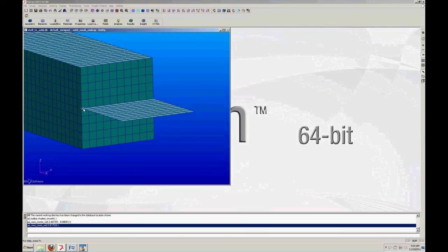Plus, you have to imagine, what would that represent in real life? That would represent in real life that somehow you gouged material out and shoved the plate inside and then welded it in. Maybe that is what happens in real life, but that isn't a common manufacturing thing. So I think in real life the weld would actually be up along here and down here. So in that case, putting a thin layer of surface elements up here and down here isn't a bad way to go.